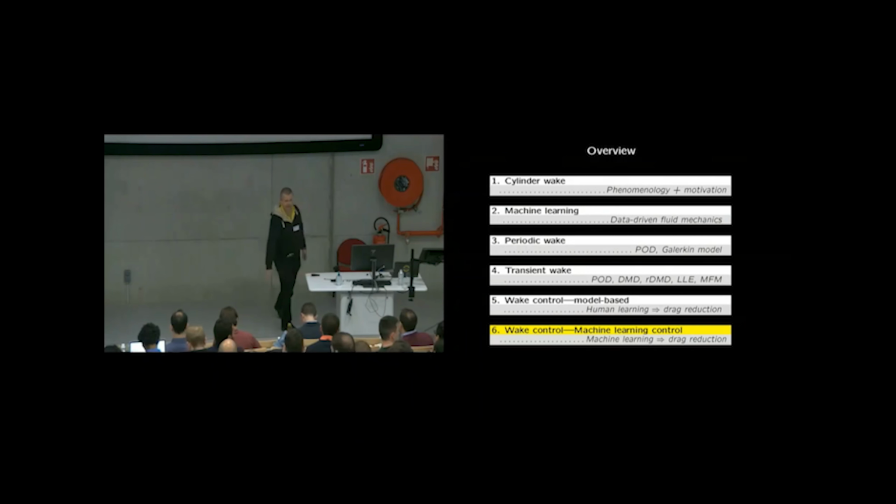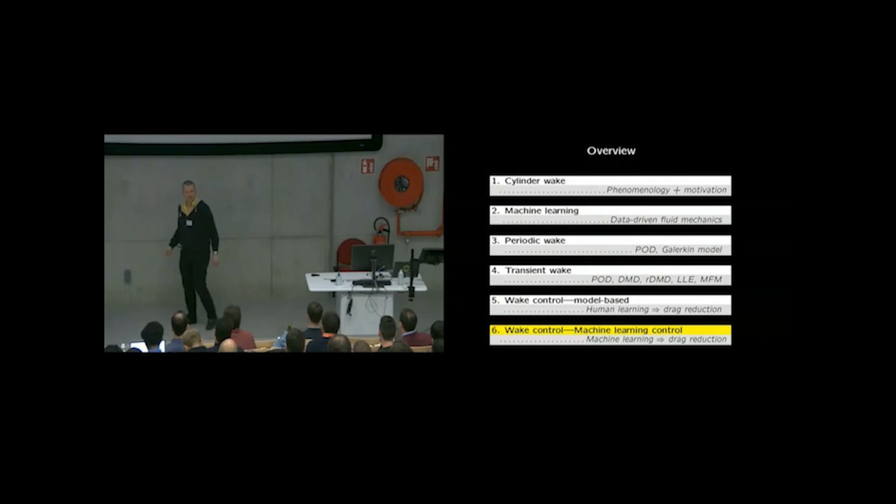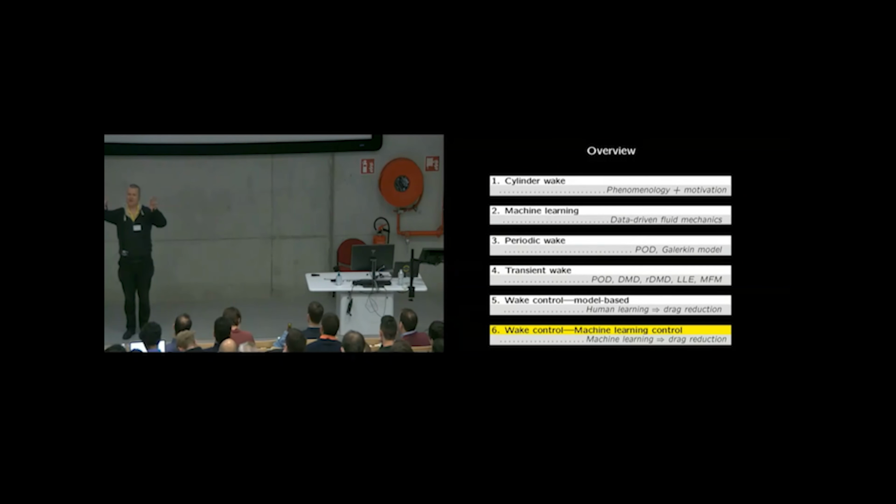Suppose, for instance, you go from a natural state to an actuated state. Good. Now, what happens? You can model the actuated states. You can model the natural state, but of course the POD modes won't correspond to each other. You have destroyed your original flow. Now, what can you do? Well, you can figure out which modes are stationary as you go from the natural state to the actuated states. One set of modes. Which modes do you have to deform?